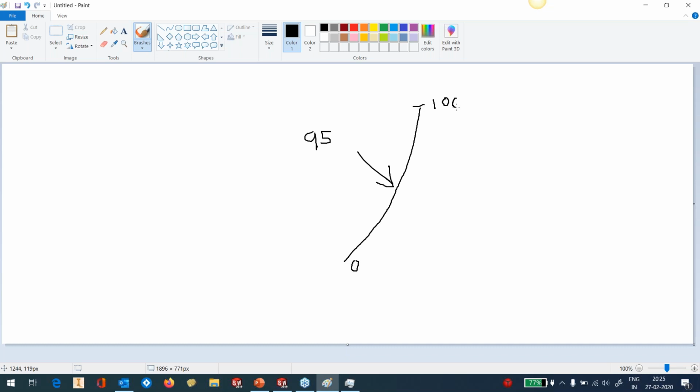So I can specify, this is 0%, 100%. So I can specify a point on this barrel profile or oval profile, let's say at 30%, and I can tell SolidCAM to keep maintaining this point in contact with the surface every time. So the moment I specify this point, SolidCAM will automatically derive the tilt angle and maintain the tilt angle throughout when it's machining the surface. So it becomes much easier.